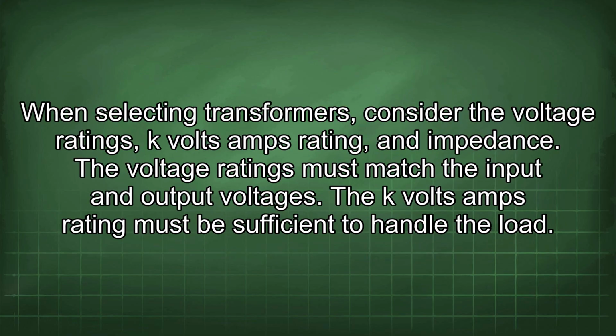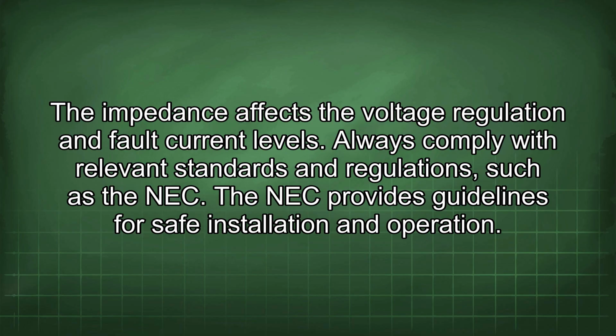When selecting transformers, consider the voltage ratings, kVA rating, and impedance. The voltage ratings must match the input and output voltages. The kVA rating must be sufficient to handle the load. The impedance affects the voltage regulation and fault current levels. Always comply with relevant standards and regulations such as the NEC. The NEC provides guidelines for safe installation and operation.